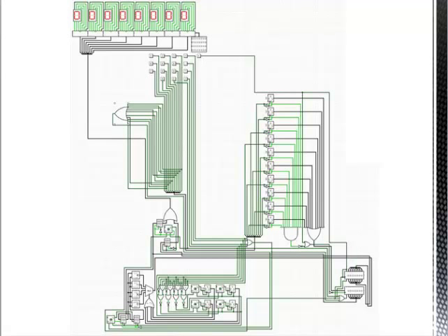This is how a 4-operation 32-bit calculator can be represented in Logisim. Each module represents a system of logic gates, in addition to there being logic gates in the diagram itself. The calculator takes and stores input, records an operation, takes a second input, and performs the desired operation.